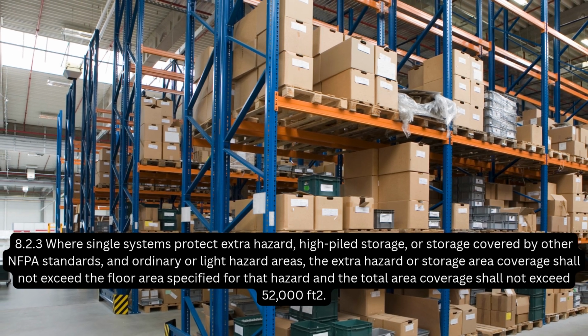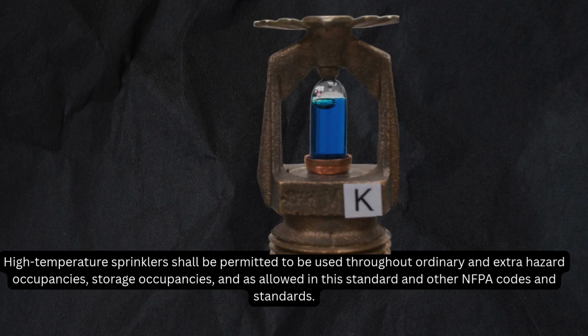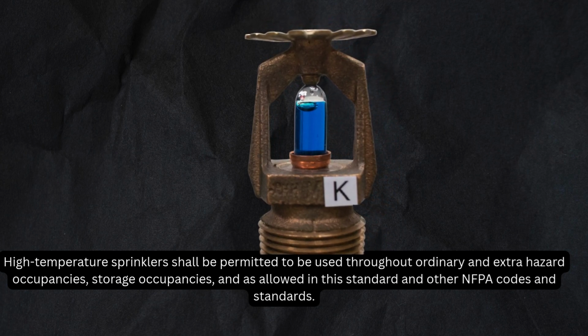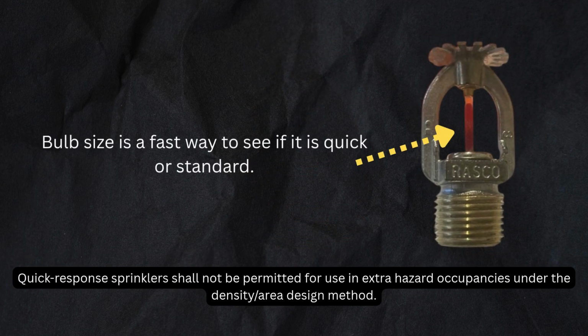8.2.3. Where single systems protect extra hazard, high-piled storage, or storage covered by other NFPA standards, and ordinary or light hazard areas, the extra hazard or storage area coverage shall not exceed the floor area specified for that hazard, and the total area coverage shall not exceed 52,000 square feet. High-temperature sprinklers shall be permitted to be used throughout ordinary and extra hazard occupancies, storage occupancies, and as allowed in this standard and other NFPA codes and standards. Quick response sprinklers shall not be permitted for use in extra hazard occupancies.